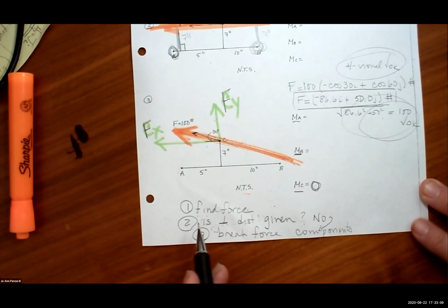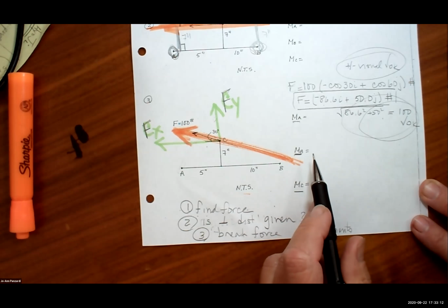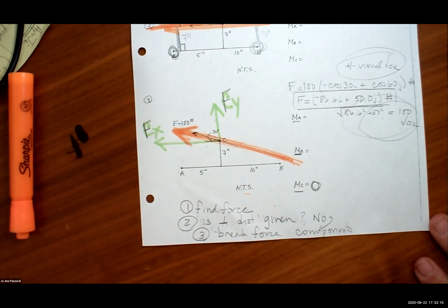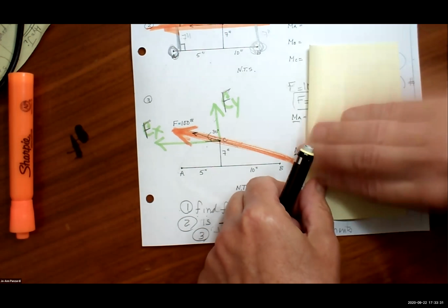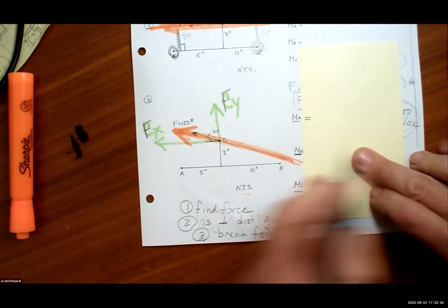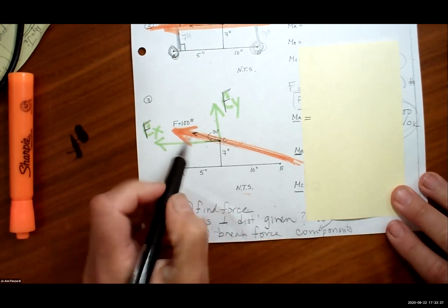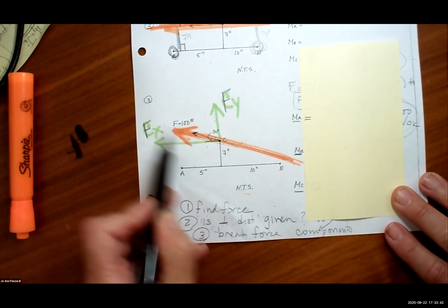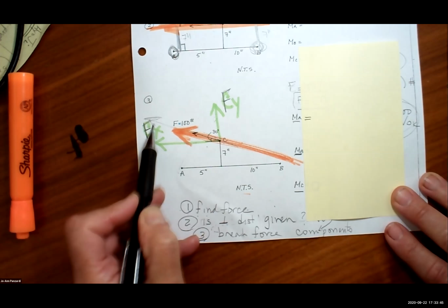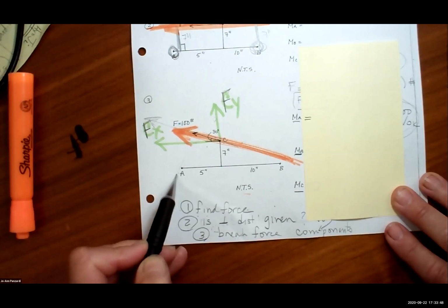Okay. Jordan. So now I want to find the moment about A, and it looks like I'm going to need to get a different sheet of paper. Everybody has the components. I'm now putting this over it. So the moment about A. If this force here is going up diagonal, is it going to create a positive or a negative moment about point A using right-hand rule?